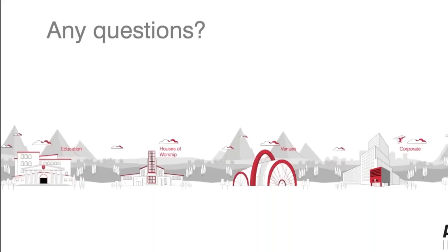Dynamic controls such as compressor and gate, once again not in the Custom Control Editor. Bear in mind, I know that a lot of people will get creative and try to use Custom Control for personal monitoring and a number of live applications, which is absolutely fine, and we are very happy to see this flexibility with the tools we give you. But the original intended main use was obviously to serve the installation market. That's why things like compressor thresholds and ratios were not necessarily at the top of our list.